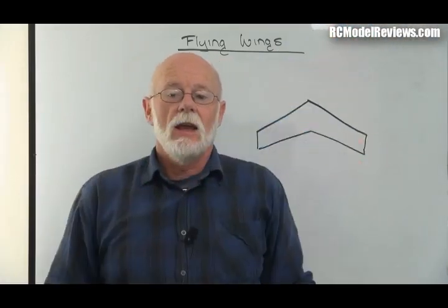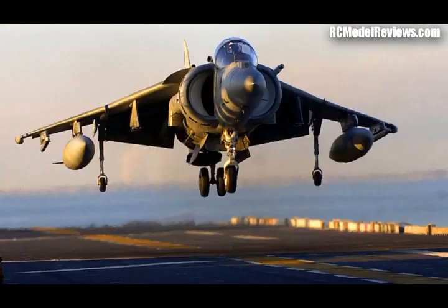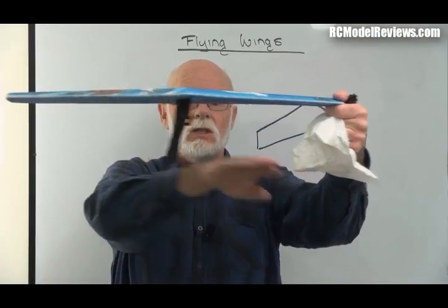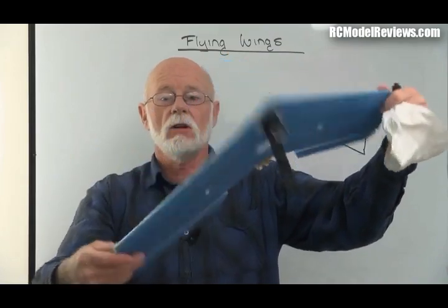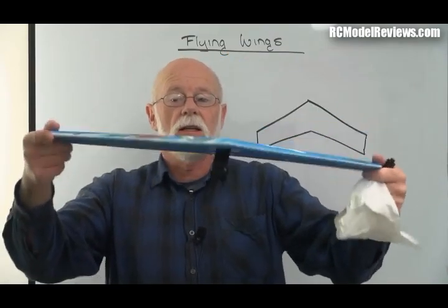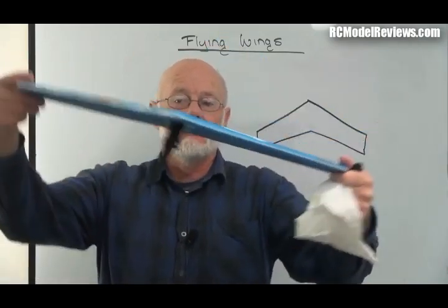level it out. So in fact, on some large aircraft, you notice on some of the big, especially military aircraft, things like the Hawker Harrier jump jet, the Alpha jet, and even some of the big cargo jets with high wing mounting, they have anhedral, they have the wings droop down at the ends. That's to counter the dihedral effect of the sweep. So you end up with a nice negative or neutral stability. Otherwise, the dihedral effect of the sweep would make the thing really rock and roll.